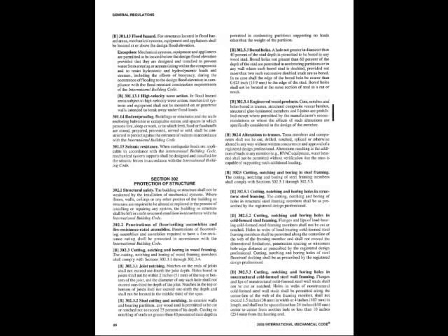Section 302 is protection of the structure. We need to make sure that anything the equipment is installed with is safe. Penetrations of floor and ceiling, cutting and notching of wood framing, bored holes. It talks about alteration to trusses, and it talks about cold-formed steel framing. Okay, we need to make sure that we never take away enough material that it makes the structure unsafe.